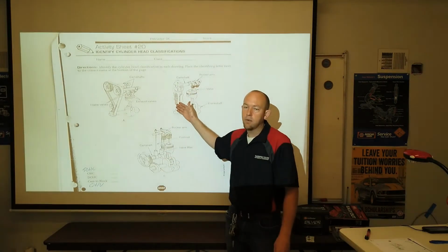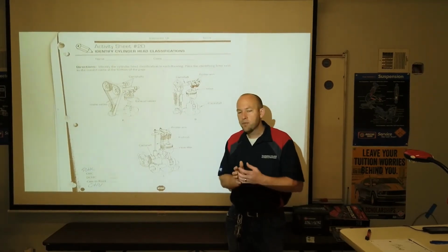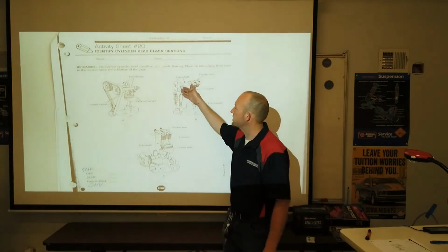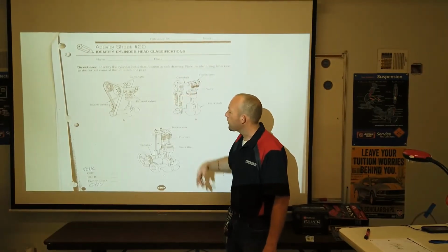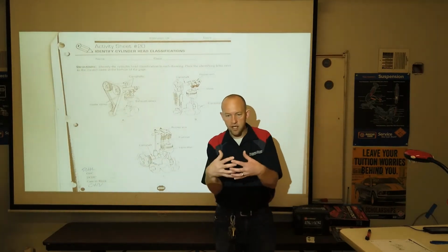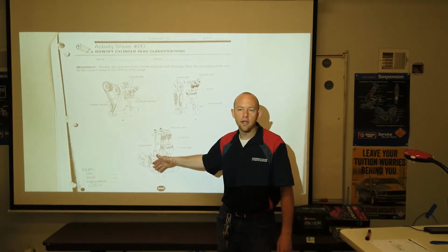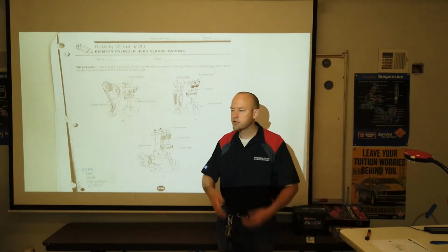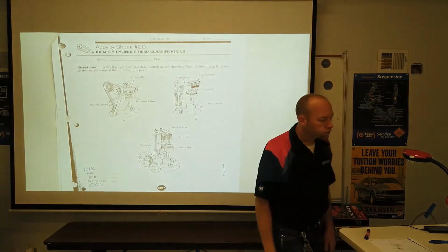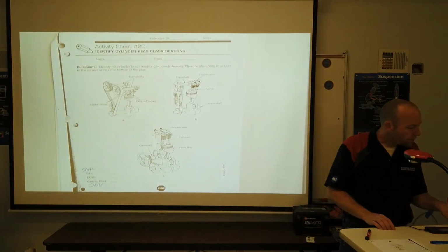This one is a chain motor. In all cases with chain motors, they're considered a lifetime component, where we don't go after them and do any repairs to them unless there is a problem with it. So this cam is connected to the crankshaft with a chain. Then on this design, it's gear to gear. They put the gears and mesh the gears directly together in this cam and block. And it's a neat sound. If you ever get around any older cars that are gear to gear, you can hear the gears meshing, whereas chains and belts are quieter. All right, I don't think there's anything else that I want to say on this one.